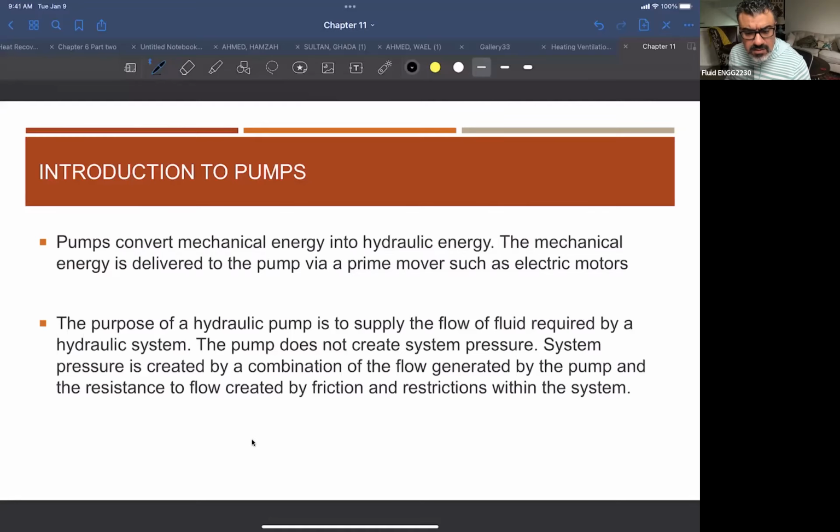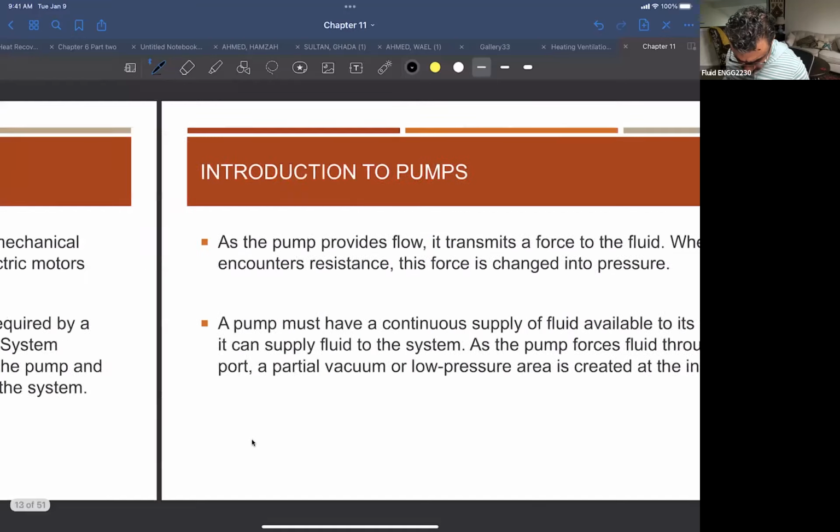Okay? This is very important to your understanding of fluid flow in this system. And this resistance we'll study in chapter 6; it could be because of friction in the piping, because of eddy losses in the piping. So all the total energy losses are considered to be a resistance. Okay, so the pump is a device that is basically there to overcome this resistance in the system. Okay.